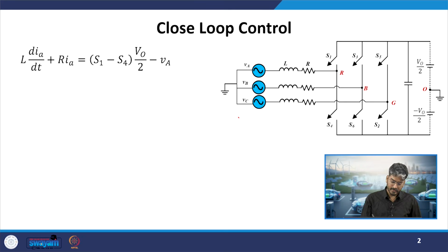Welcome back. So in the last class we started our discussion on closed loop control of our 3-phase VSI, where we saw the requirement of DQ frame control and its advantage. In 3-phase AC, where we will have high power chargers, we have to go for 3-phase AC as per the grid requirement. When we connect 3-phase AC to our charger, we are interested in controlling two parameters, our active and reactive power flowing through the charger or exchanged with the grid.